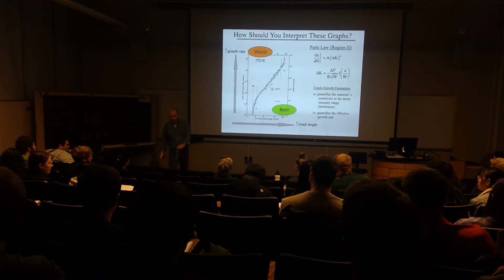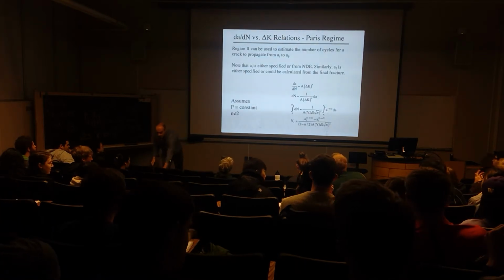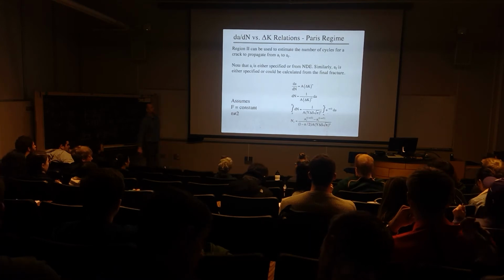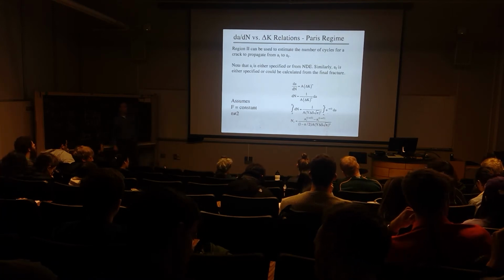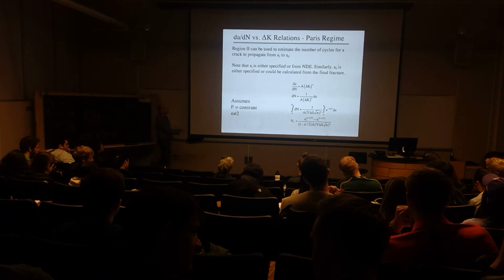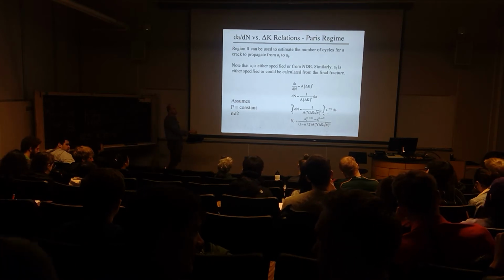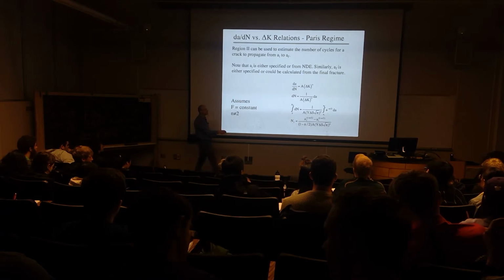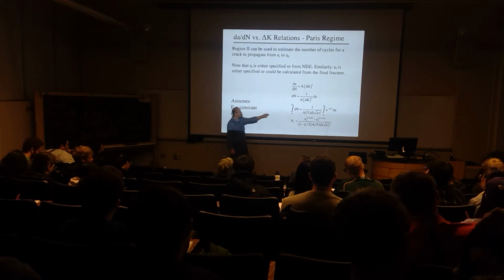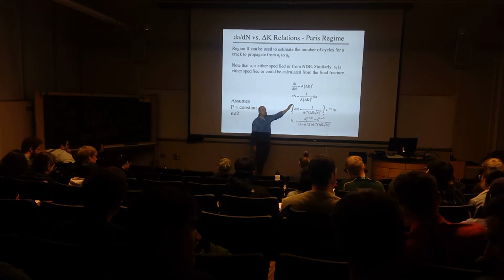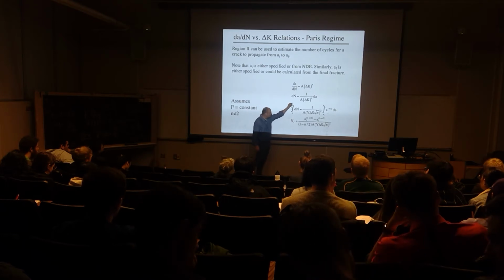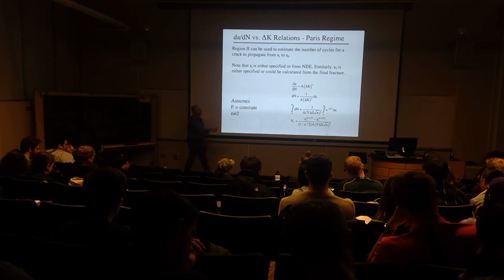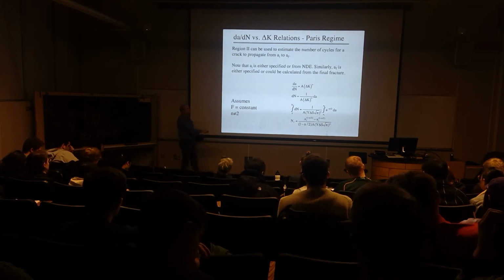Good, great. So now we're going to apply this to failure analysis. We can estimate the inherent life in our structures just by taking that relationship with Paris law, rewriting it in terms of the stress intensity range, and then integrating from 0 to the final number of cycles, which we define to be an apparent limit for that particular structure.